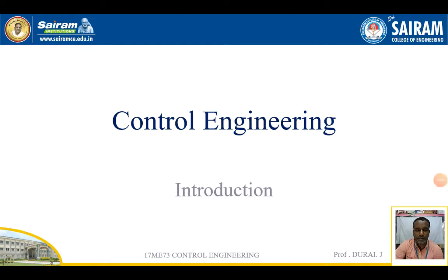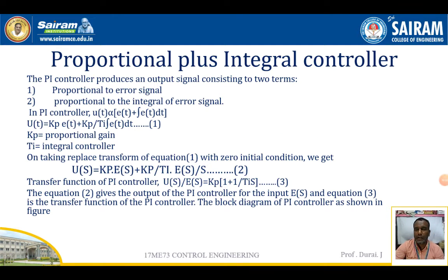Good evening everyone. In this video we are going to discuss the proportional plus integral controller. Here the PI controller produces an output signal based on two terms: one proportional to the error signal and one proportional to the integral of the error signal.